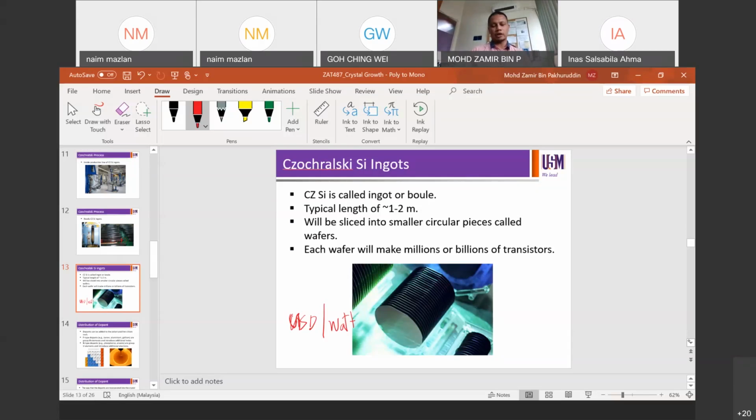And one way to do that is by reducing the thickness of the silicon wafers. So you can't afford to use 500 micron silicon wafers for a solar cell production line. Okay, so that's why the current 180 micron. And in fact, the industry is going for thinner and thinner wafers in order to minimize the dollar involved in the manufacturing. But it comes with another drawback.